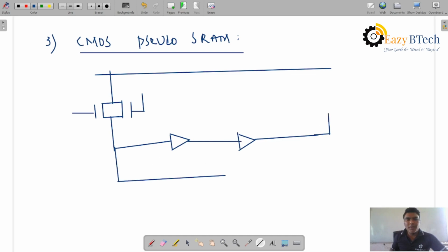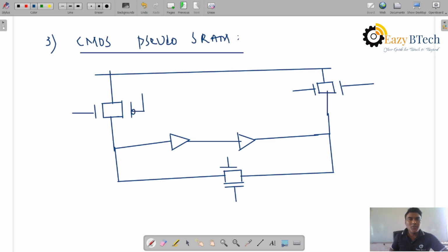Same thing, but replacing T1, T2 and T3 by pass transistors. It is what we call a transmission gate. So it will be on for any logic we can give, whether it is 0 or 1. This is designed by PMOS and NMOS. This is inverter 1, inverter 2. Let me write here: this is the bus line, 1-bit data stored, temporary storage data, 1-bit data storage.